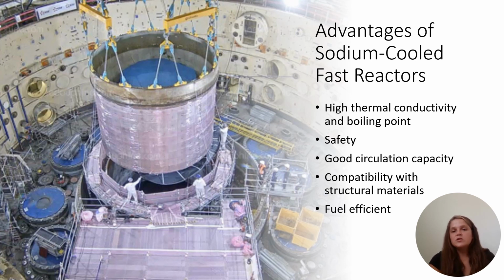Another advantage to the sodium-cooled fast reactor is safety. So the coolant needed to submerge the core can be maintained without being pressurized. So again, it's that pressurization that's keeping us afloat here. They also have excellent natural circulation capacity because of their high conductivity and high system temperature difference, and the large temperature difference between the core inlet and the outlet coolant.